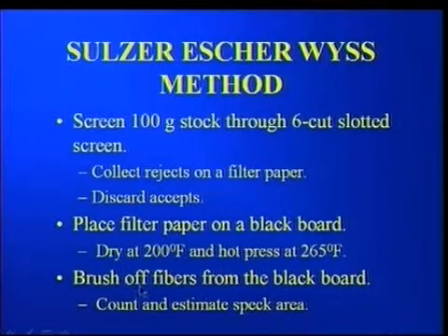We brush off the loosely held fibers, but what happens is that stickies will pick up the fibers from the filter paper and will appear white, and we count these white specks on a blackboard by going through image analysis or by manual means.